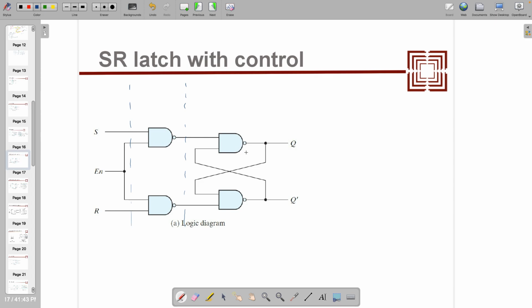If all of them have 1 nanosecond of propagation delay, that's 3 nanoseconds, right? Because of 3 tPD of NAND, these 3 will be on the critical path, either on this side or maybe the other side. Any side will do, because both are in parallel, right? Okay, now let's proceed further.